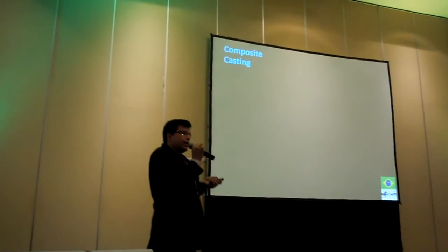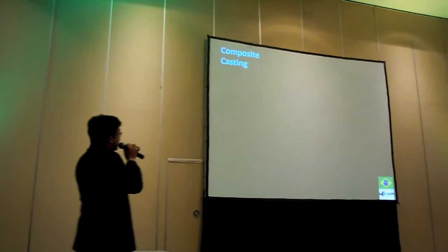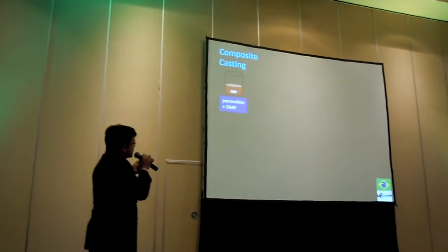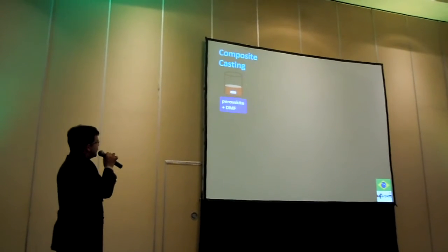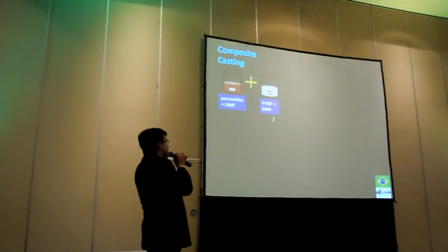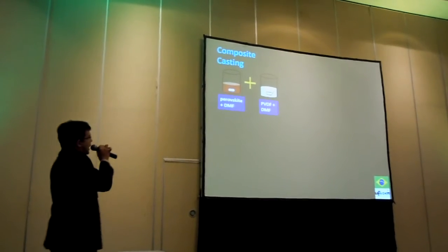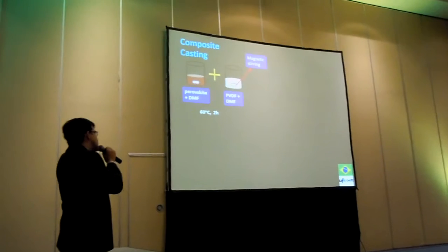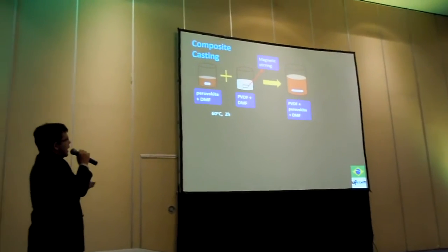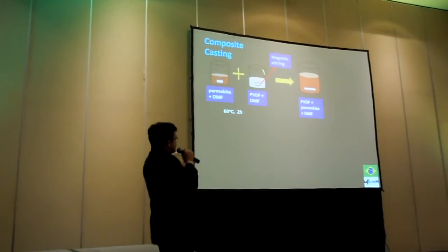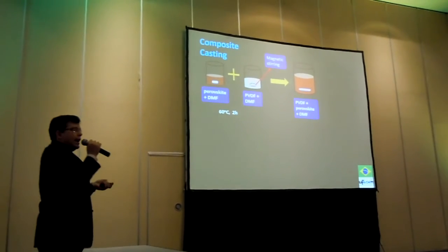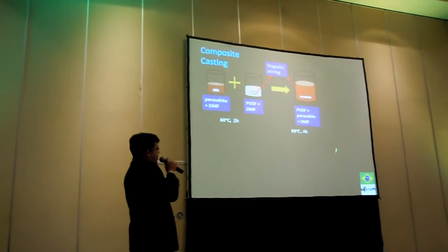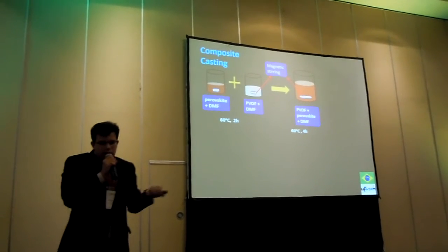Then we mix it with the polymer, making a casting wave. So first we make a suspension of perovskite in DMF and a solution of PVDF in DMF too, with magnetic stirring for 2 hours at 60 degrees. Then we put the suspension and the solution all together, and it was magnetic stirring too, for 4 hours now, but still at 60 degrees.